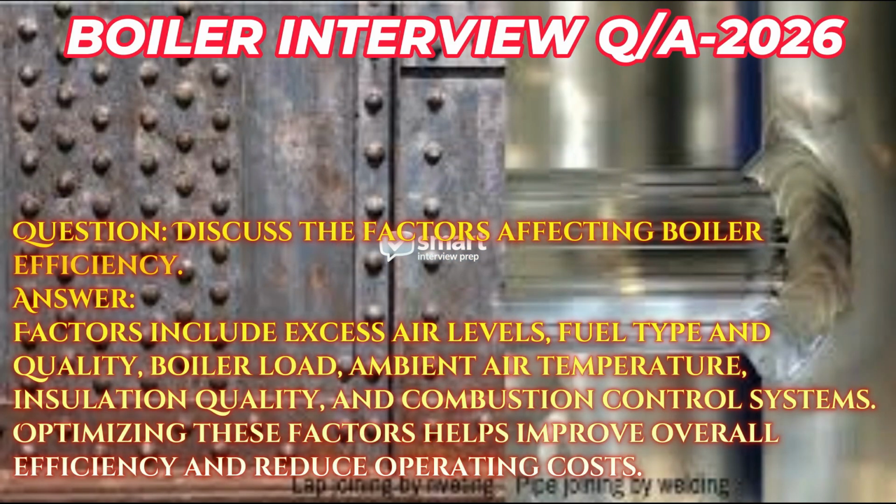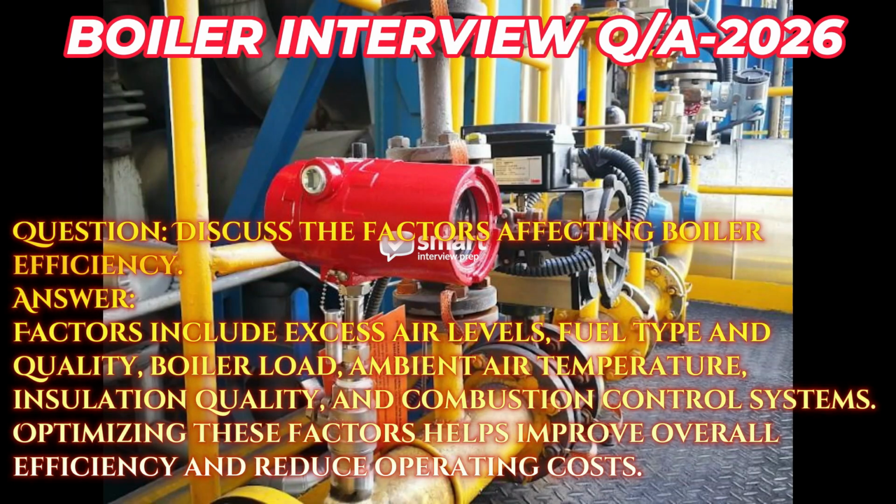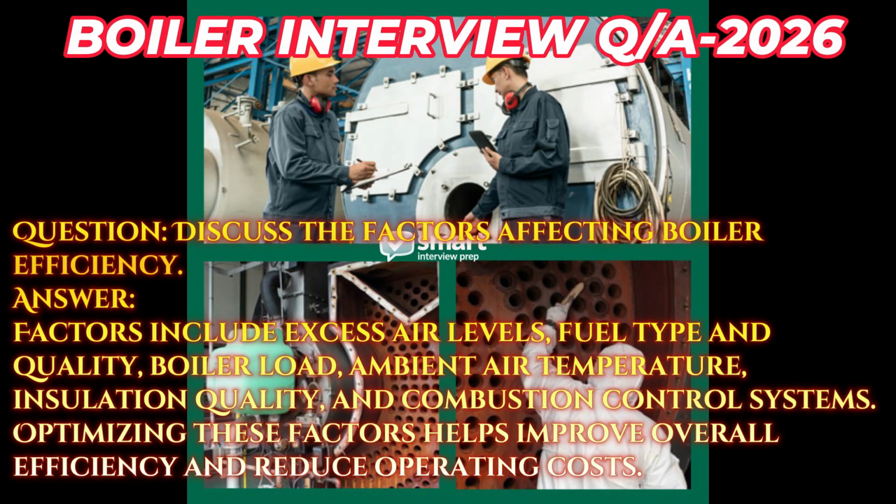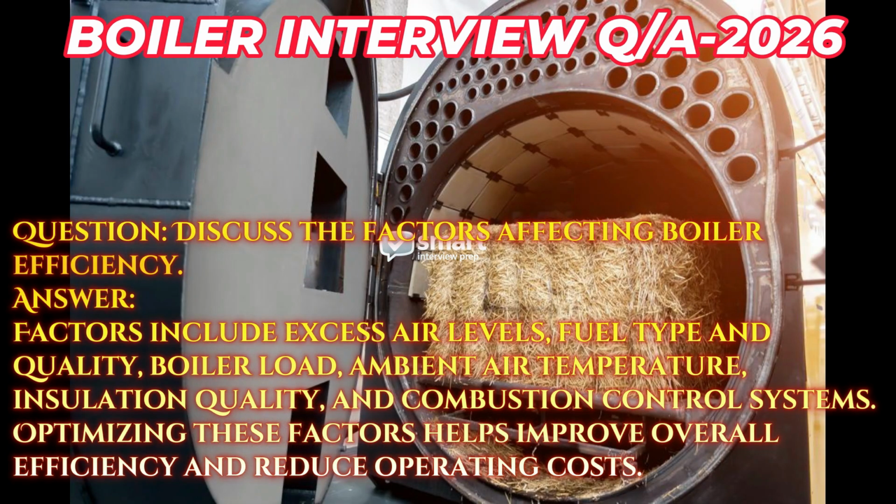Question: discuss the factors affecting boiler efficiency. Answer: factors include excess air levels, fuel type and quality, boiler load, ambient air temperature, insulation quality, and combustion control systems. Optimizing these factors helps improve overall efficiency and reduce operating costs.